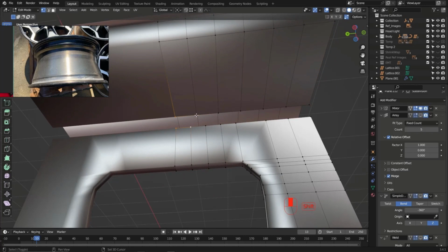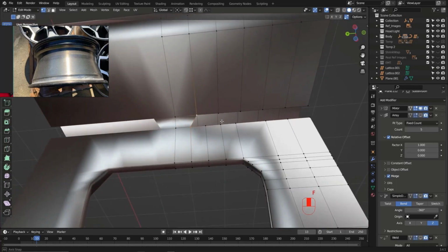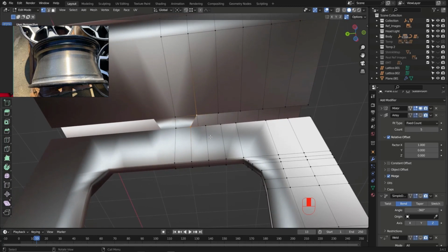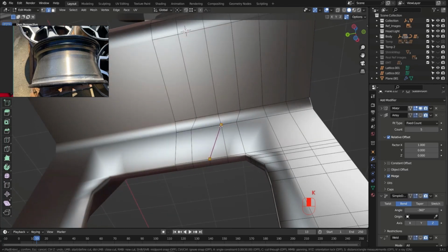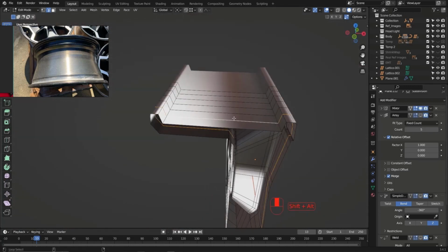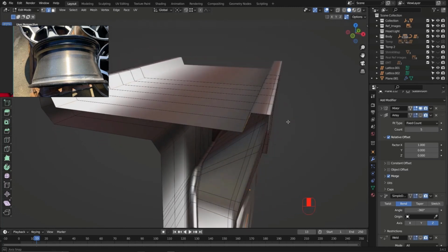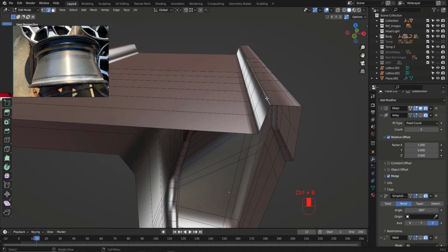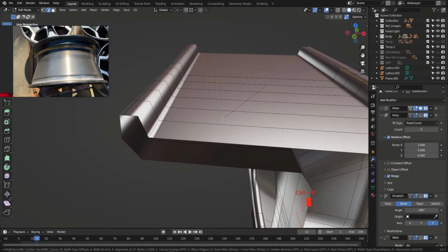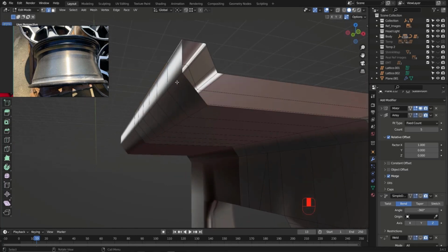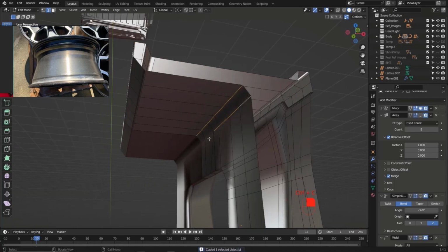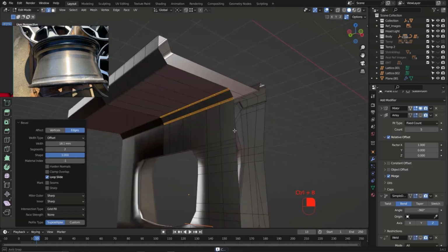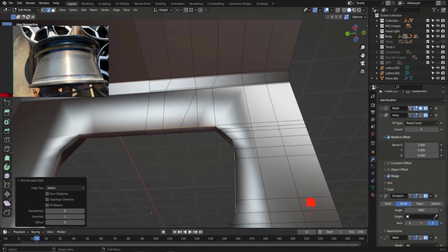All right, let's grab those, hit F to create a face, and I think the number of the vertices is not equal. In this case, maybe I can delete this one, grab this, hit F, and create another face like that. And this one you can end it right here if you like. Already grab these, this one, bevel it with Ctrl B, grab this with this one, bevel it with Ctrl B, this one and this edge, hit Ctrl B and bevel it. Those over here, Ctrl B, sorry, grab this one and bevel them like that. And this area as well, you should bevel it.